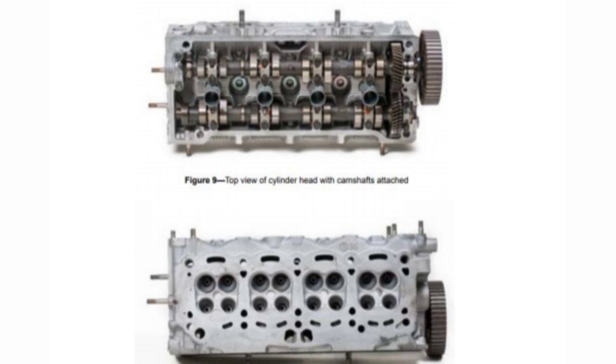It serves as a cover for the cylinders and pistons. The cylinder head helps to create the top part of the combustion chamber. An engine breathes through the cylinder head. It lets an air or gas mixture into the engine and exhausts out of the engine. The valves on the valve train control the breathing of an engine by opening and closing the valves at the appropriate time.